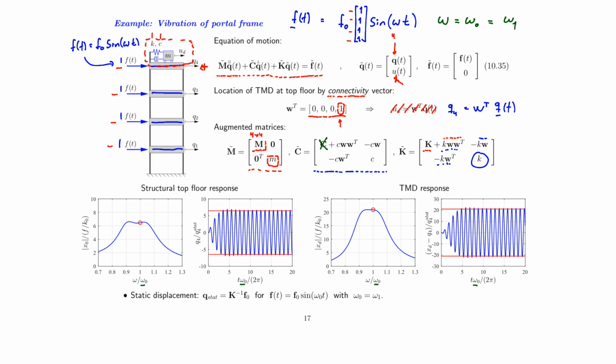The figure to the left shows the dynamic amplification curve for x0. At resonance, we see that the amplitude is about 6, or the dynamic amplification is about 6, and of course we get a slightly smaller amplitude if we excite it a little bit less than omega 0, but in principle, around the resonance frequency in this bandwidth here, we will have an approximately flat plateau represented by this curve here.